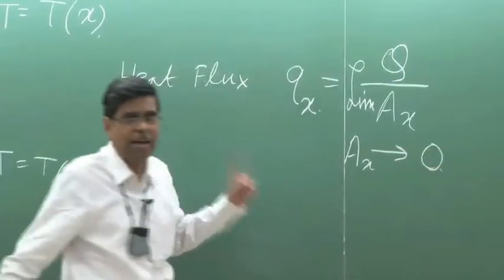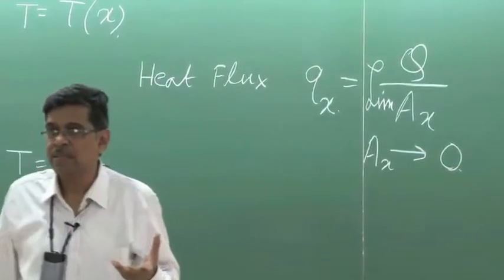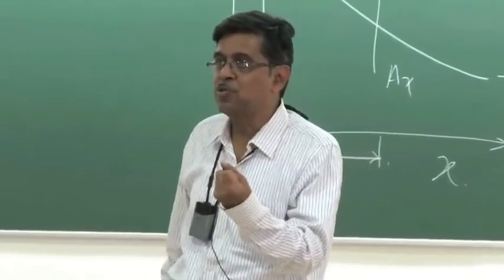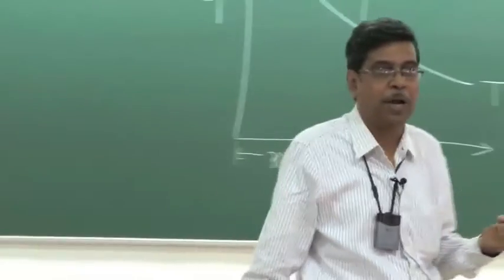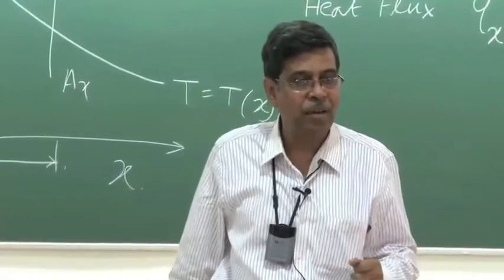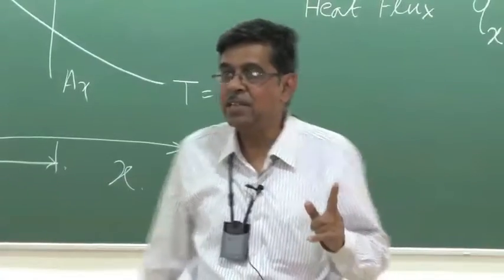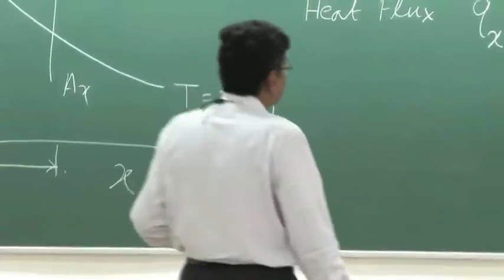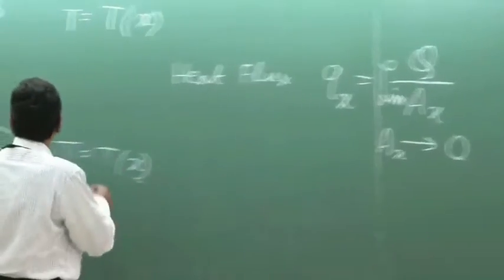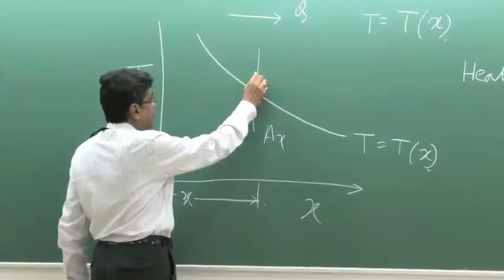Now it is very fundamental and basic, like the stress, that the heat transfer reduces to 0 when A reduces to 0 at a point, but their quotient attains a finite limiting value, and that is the heat flux, that is the amount of heat per unit area, and therefore this gets a definition at a point.